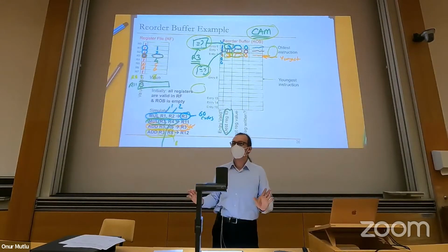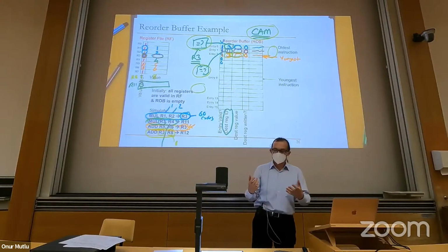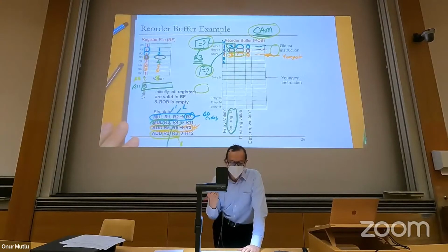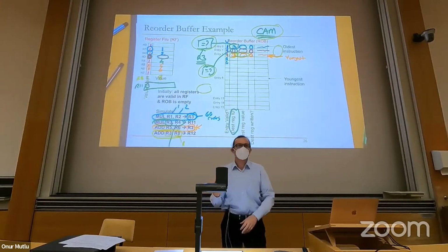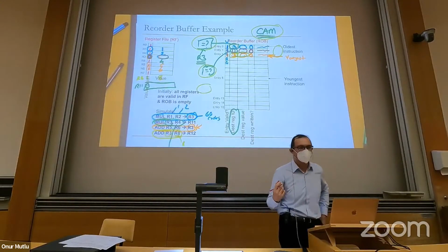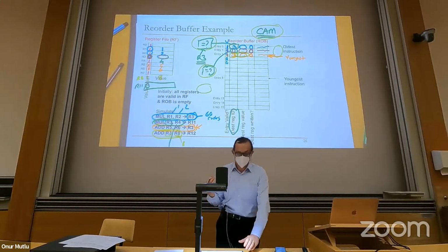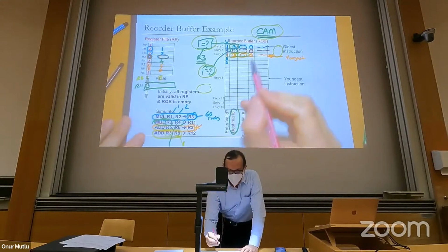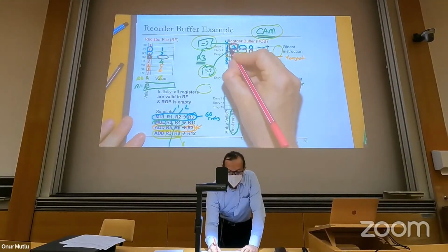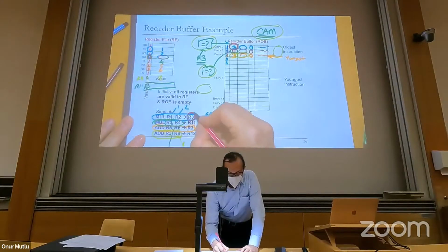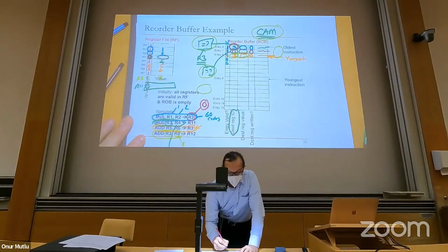Is this clear? Okay, so there's one more thing that I should actually say over here. Now what we've done is something even deeper than you may realize, which is really the soul of out-of-order execution. I'll handle your question very quickly. So now R3 is here. There's one definition of R3 here. That's just the multiply. It's in reorder buffer entry 0, right?